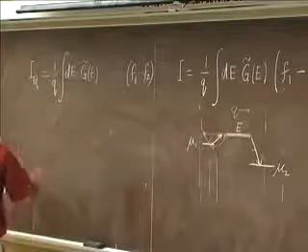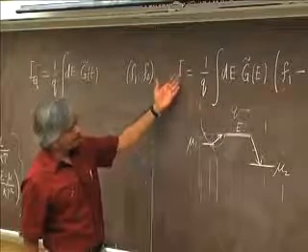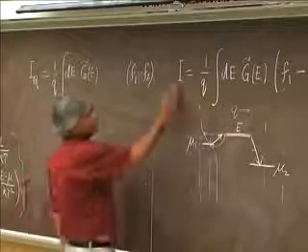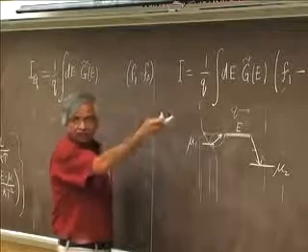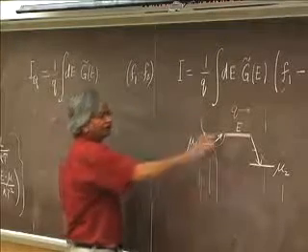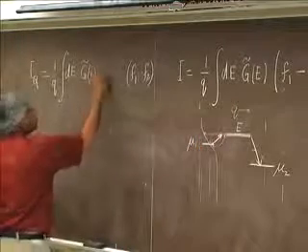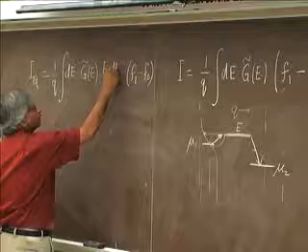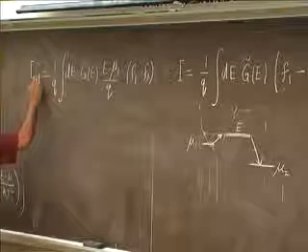So we had an expression for I. If I wanted the rate at which electrons go through, then I should have divided by a Q. That would give me the rate at which electrons go through. And then every time an electron goes through, it removes that much heat. So what I should do is put an E minus mu1 over Q here, if I'm writing the heat current at contact 1.